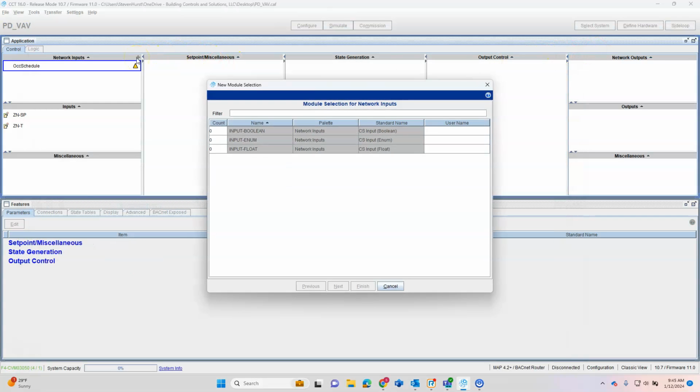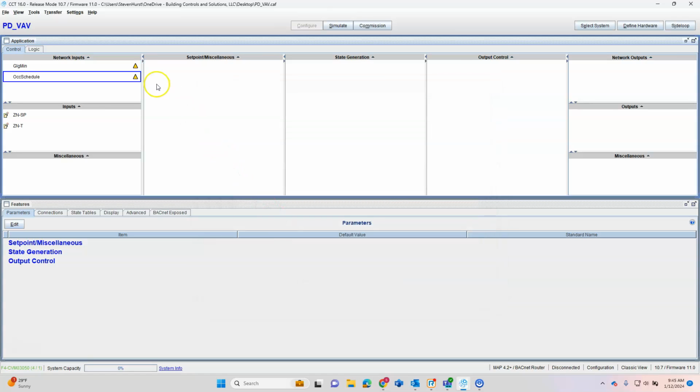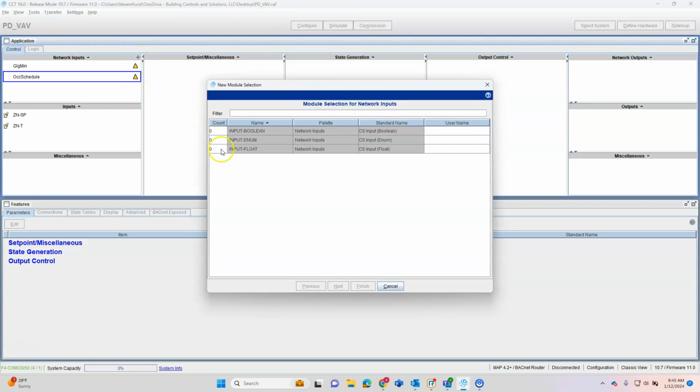And for a VVT system, we need some min and max settings for cooling and heating. You never want to go to zero unless you're unoccupied. When the building's occupied, ASHRAE guidelines say you have to have so much flow. So let's set some cooling minimums: cooling min, cooling max.